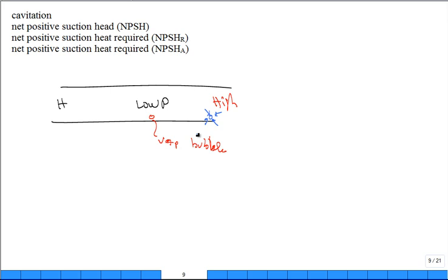So what exactly is it again? Gas or vapor bubbles forming in low pressure regions, flowing over, collapsing, and then impacting and sending a significant pressure pulse through, and it impacts the solid material, like a boom boom, like hitting it with a little hammer, right? Or sandblasting it. Maybe that's a better analogy, because the effects of cavitation look like somebody sandblasted it after a long time in rotating machinery.